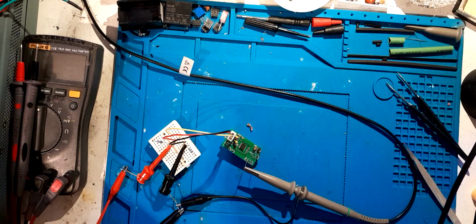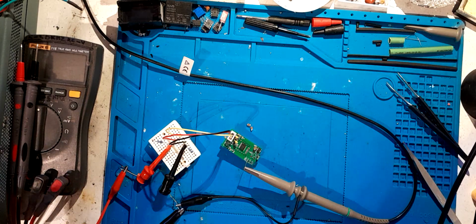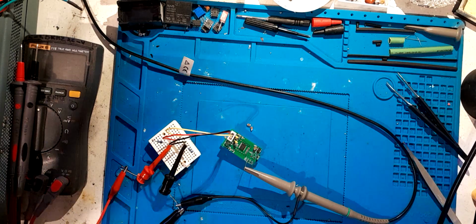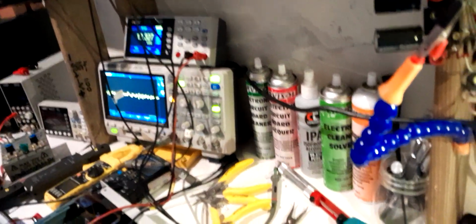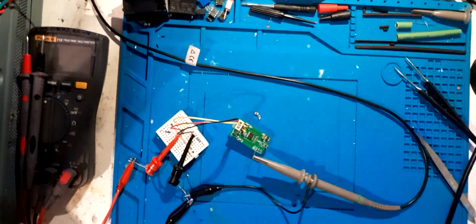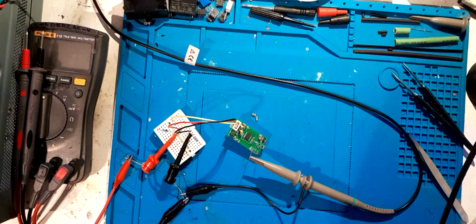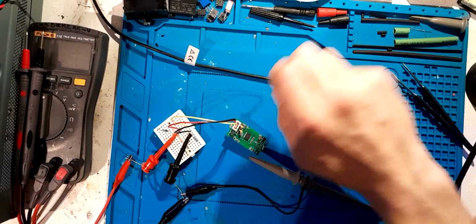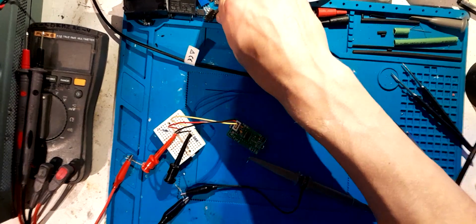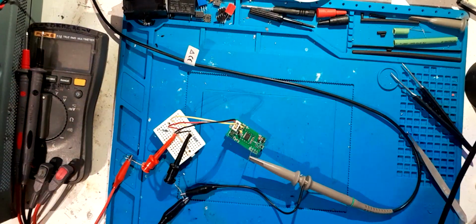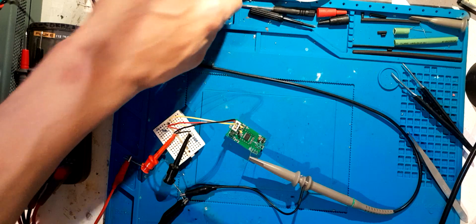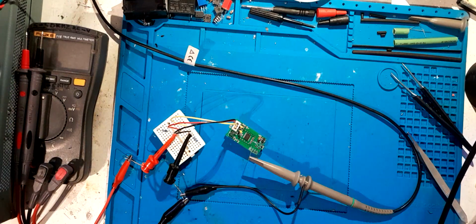So we'll just check that quickly. Yeah, back to 100 millivolts. Yeah, that might even be smaller. I think that's the sweet spot. I really think that's the sweet spot, 20 microfarads. So I'll keep these two other capacitors here with these parts. These parts are for my power supply stuff that I'm in the middle of doing. I'll leave them there so that I can put them on the other board.